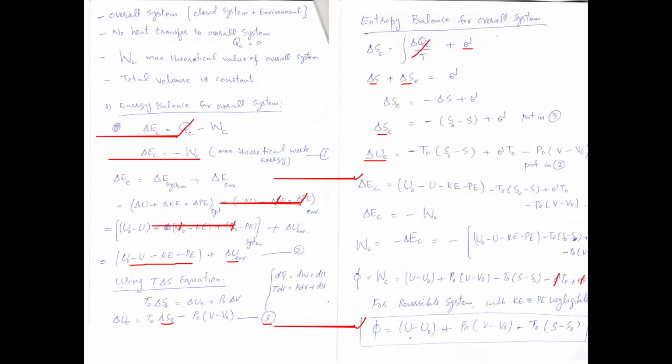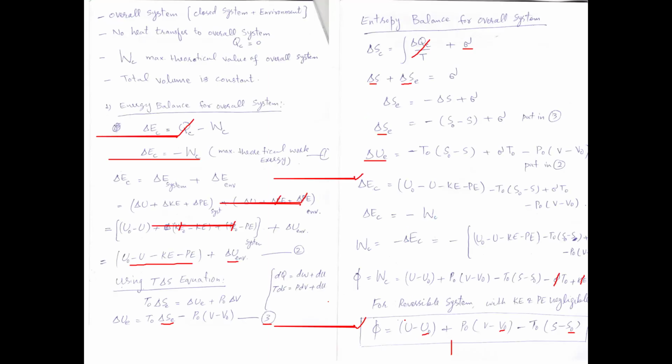What we need is basically two states. One is the system state, I mean internal energy of the system, specific volume of the system, and the entropy of the system. And the other property we need is the reference, I mean the environmental property, like what is the state of the system at environmental condition, right? This is the state of the condition for the environment. Normally the properties that are given in the property table are specific properties, right? I mean the absolute properties are not available. We have to multiply with the mass, then we can get the total value of that.